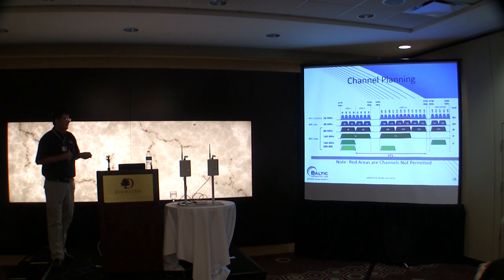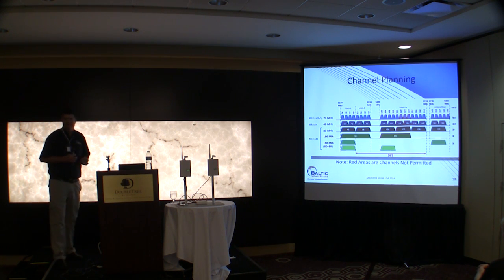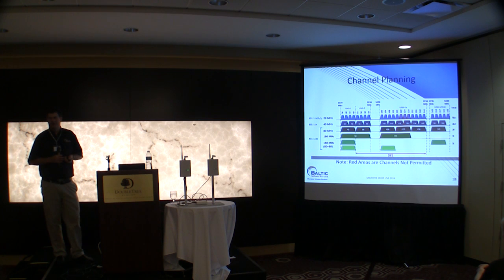You can see on our 80 megahertz channel widths, we only have 5 non-overlapping channels. That gives you enough for a four-sector tower and 1 backhaul. And you've blown through all your spectrum. So, I don't know how good 80 megahertz is going to be in a real live environment long term, but only your environment will determine that. Eventually in the 160 space, there'll be something called 80 plus 80. It'll actually let you split across the band and do 80 here and 80 up here versus having it all contiguous.